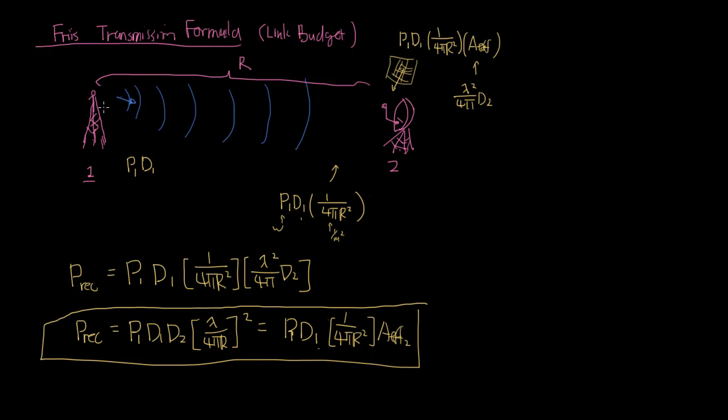You can think of it as the farther away the transmitter and the receiver are in units of wavelength, the more diffuse the power is going to be. So as you increase in frequency, your transmitter and your receiver are now effectively farther and farther away. So you take a much larger penalty due to this diffusion that occurs as you propagate outwards.